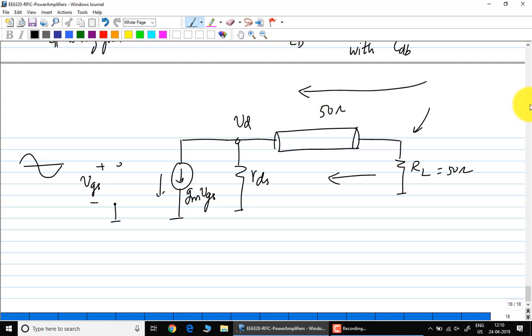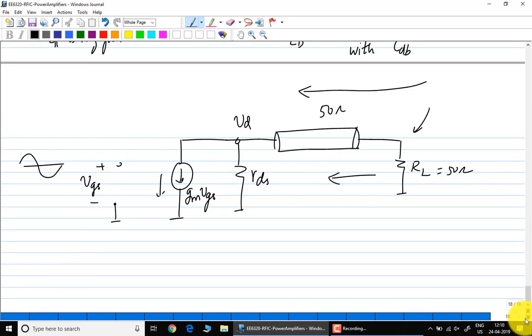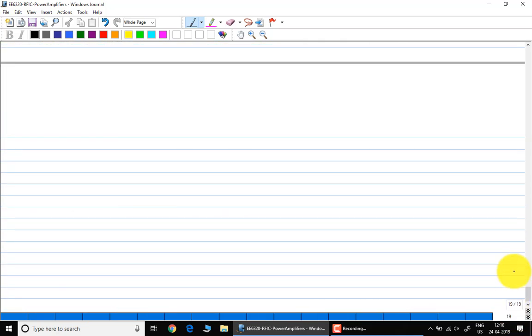Okay, let us come back to output matching. How do you do output matching for the PA? So now, what sort of signal comes that is absorbed by the antenna from outside? It could be other signals, wireless signals. It could be your own transmit signal getting reflected back from a very nearby interferer.